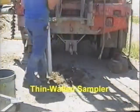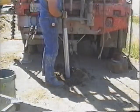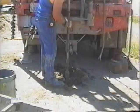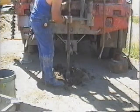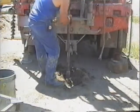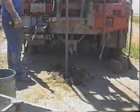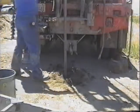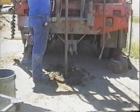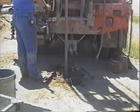Thin-walled Shelby tubes are commonly used to obtain high-quality or relatively undisturbed samples. An undisturbed sample is one obtained with sampling techniques designed to preserve as closely as possible the natural structure of the material. These samples are suitable for shear, consolidation, and permeability tests, as well as for all tests performed on disturbed samples. However, a certain amount of sample disturbance is inevitable, regardless of the sampling method used, and thus the term undisturbed sample is only a relative term.